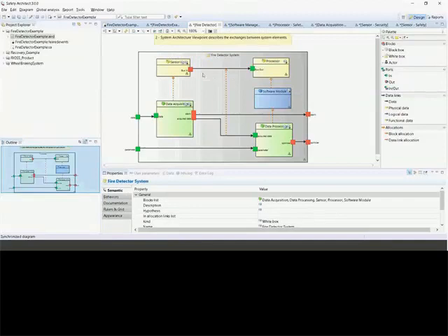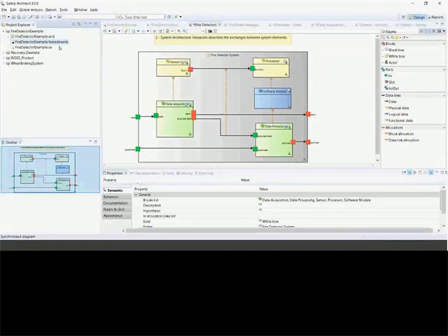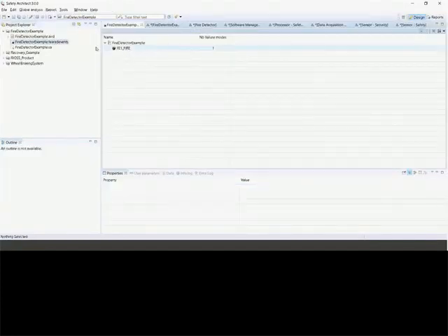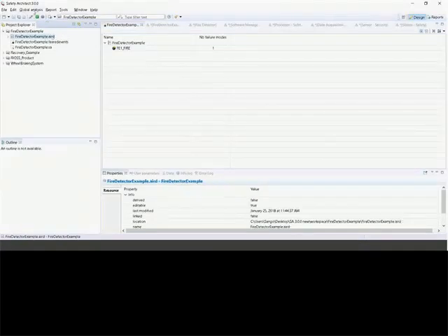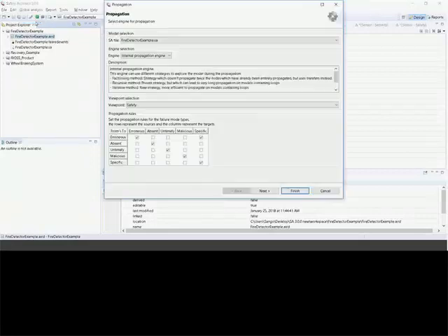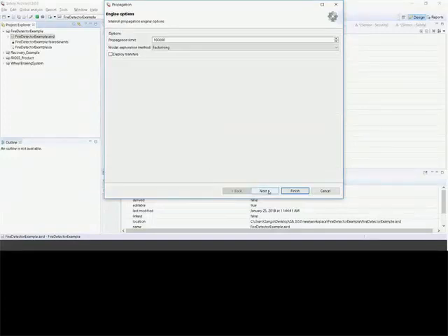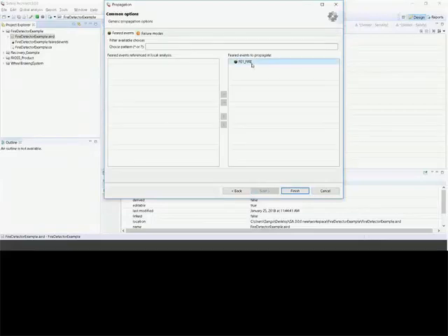So now you can generate the propagation of this failure or this security artifact to see how we can have the failure event. To do that in Safety Architect, you can just go in global analysis, run propagation, and in the propagation, you can select your viewpoint. For example, here I can select to see the propagation of my failure in the safety viewpoint. So I can just generate the propagation for this failure.